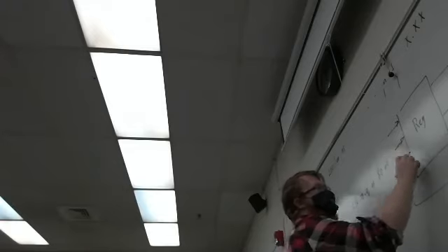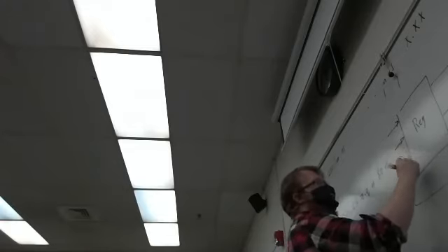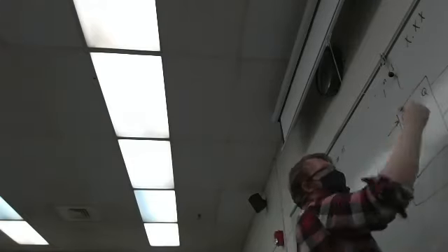This guy, we can more or less consider to be a D flip-flop, because that's what registers are. It's just a bunch of D flip-flops. And so we know that when a clock happens, it takes 80 nanoseconds to update from whatever's here and put it on the Qs.